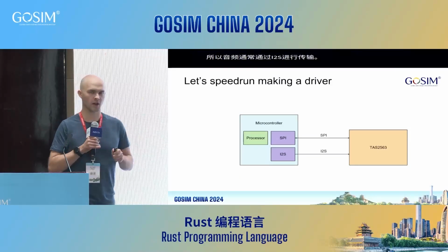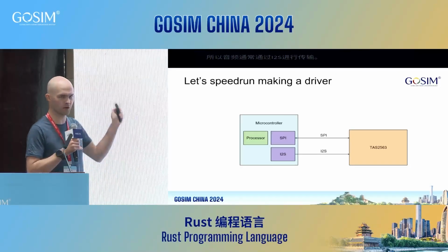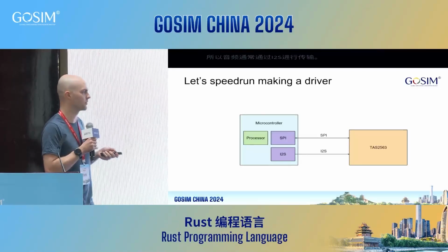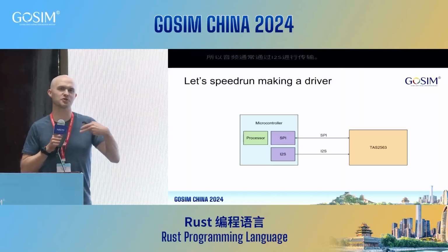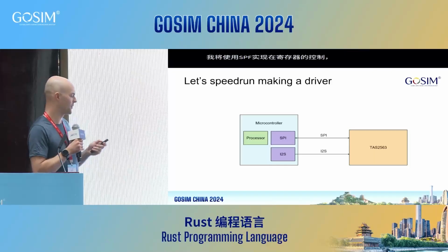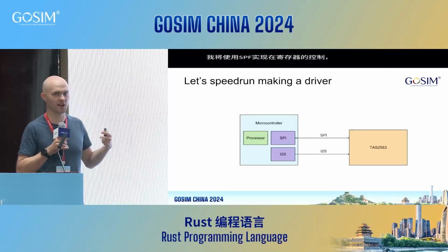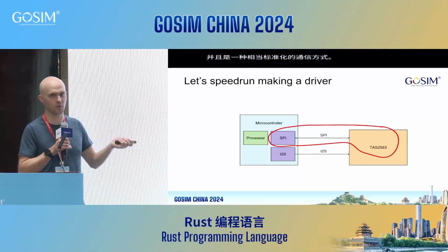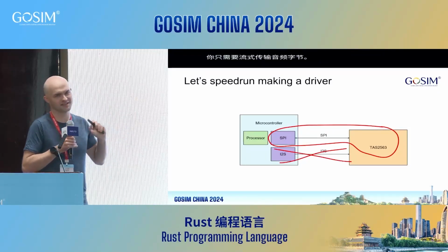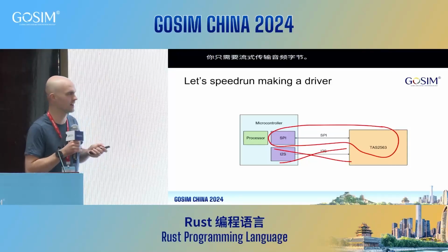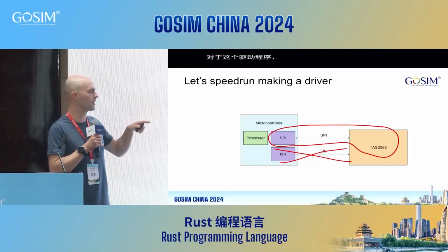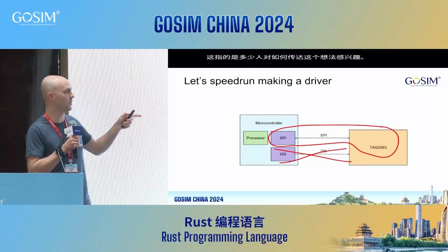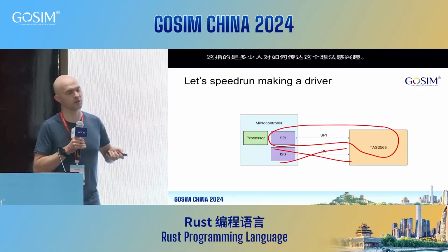But sending audio is more of a task of the microcontroller and is a pretty standardized communication method. You just basically stream your audio bytes. So for this driver, we'll mostly consider the communication bus to set commands, and not so much how to send audio. We'll use the SPI bus to configure at what clock frequency I2S should be operating, but not send any audio itself.